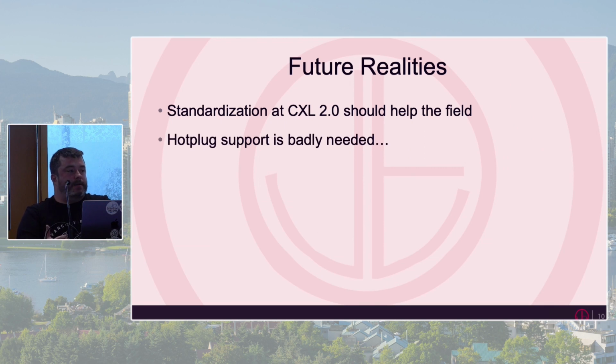So in shops that use FPGAs a lot, when you reprogram FPGAs, depending on how you have the chip layout, you may have to basically reboot the FPGA. Like if you overwrite the PCIe block or the CXL IP, then you have to reboot the card so it can retrain, right? In CXL 1.1, there is no hot plug, which is very challenging for anyone.